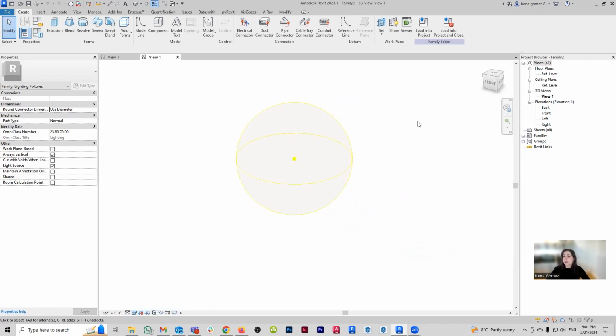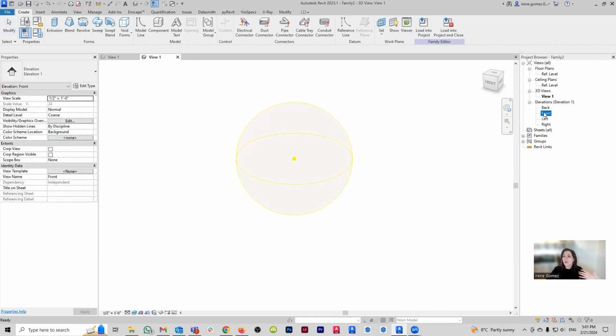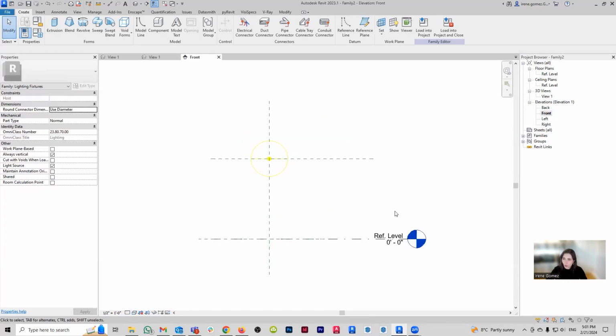So now, because I'm going to be modeling the geometry of my object, my recommendation here is that you bring a reference. In an ideal world, you would have an AutoCAD or a DWG or line work of that family. I went searching for this one and I couldn't find it, unfortunately. So instead, what we're going to do is work with a photograph and some general dimensions. Is this ideal? No. Is it better than nothing? Yes. So, you know, you roll with the punches, so to speak.